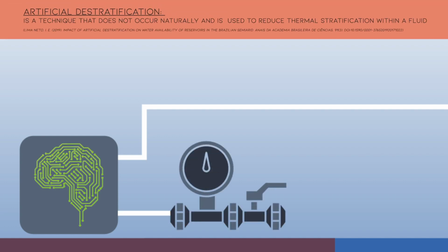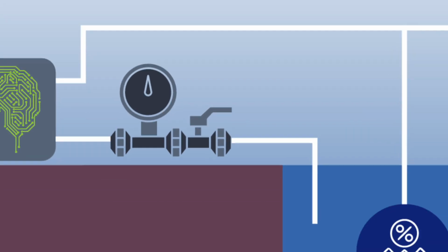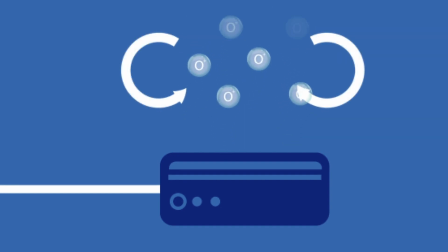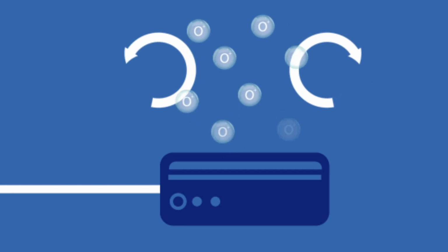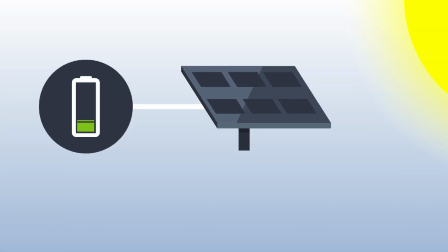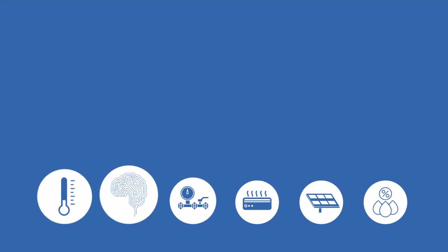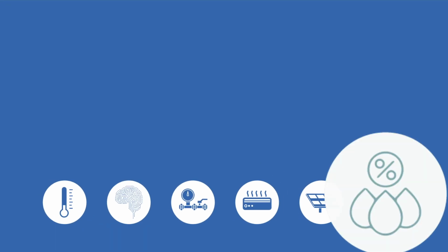And utilizing a simple process called artificial destratification, oxygen is fed through tubes to the diffuser, which introduces oxygen back into the lake system. The bubbles that rise induce a vertical mixing within the water that help with this destratification. To ensure an efficient, yet eco-friendly project performance, the entire pond system runs entirely on solar energy. Let's dive deeper into each component and the design process along the way.